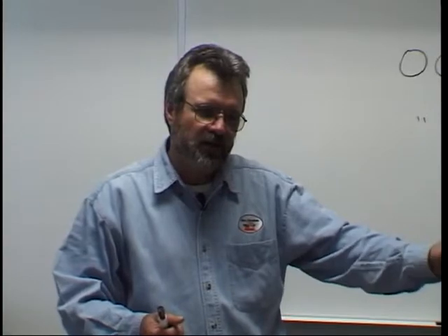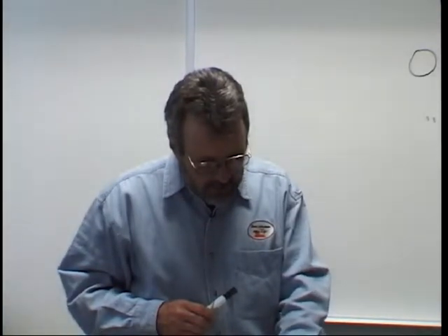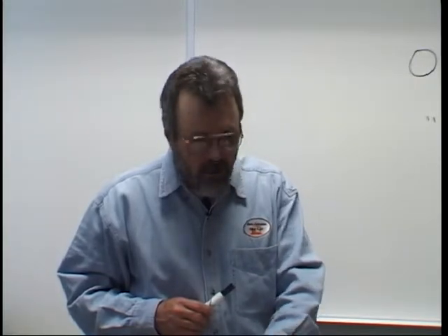And when I'm setting my machine, sometimes I'll reach out there and change that, but typically I'll set the voltage first, and I'll reach out there and change my amperage. But you can do it the other way too. You can set your amperage and then dial it in with your voltage. I've just found it easier to do it with the voltage by presetting the voltage. But even once you've got it preset, some machines have a fine tune to where you can just dial it in and get it down to just as perfect as you can possibly want it. So this permits the operator to obtain exact welding settings under welding load conditions.